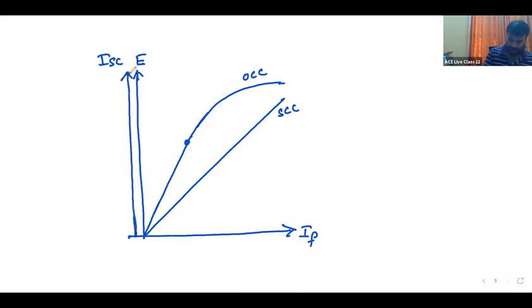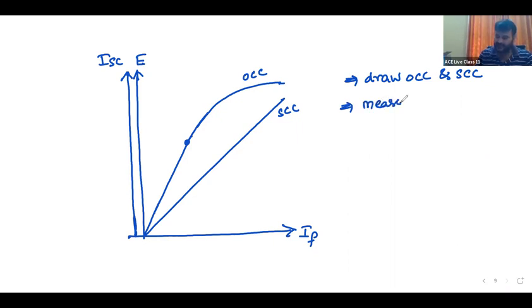Let us make it fast and we have to come to the questions mainly. With the knowledge of OCC and SCC, measure the synchronous impedance. First step is draw OCC and SCC. Next, measure the synchronous impedance.